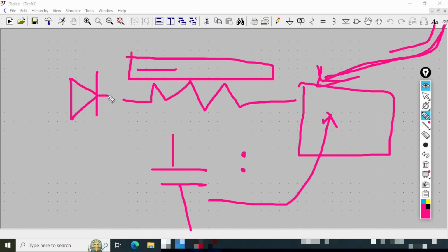So this schematic editor will help you to ease the node connections. That means this node and this node, say we are connecting here to here. This is very cumbersome in spice if we have a huge number of them; this interface will alleviate that. But however, if you are thinking that you will skip the spice command related stuff by this editor, no, that you cannot do. You have to do that by using this .op. .op is generally the operating point and it is mentioned at the very beginning. I have already explained in the spice command episode.